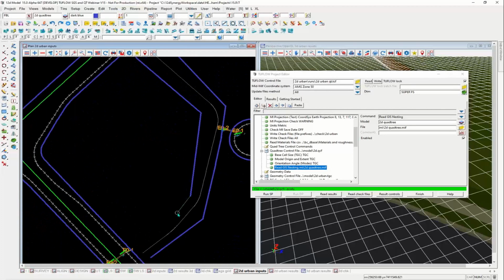Generally, you don't want to interact. Usually, you'll try to be more specific about it. When you get to the end of your polygons, it's important that you do close them. With the trace function, you just hit C for close. So essentially, I haven't drawn a very accurate one, but that's all that's needed to draw a new polygon.